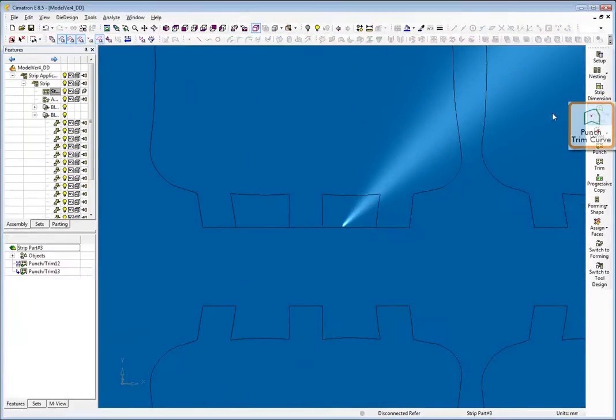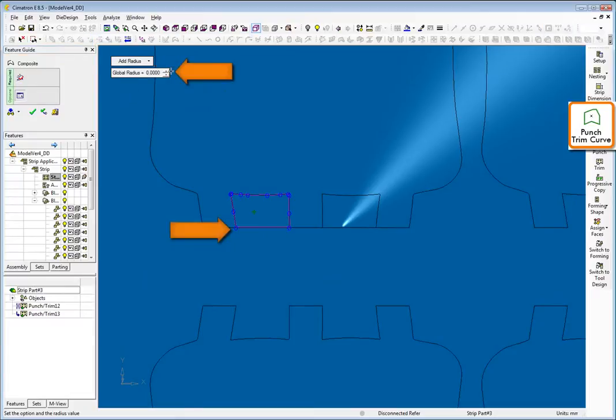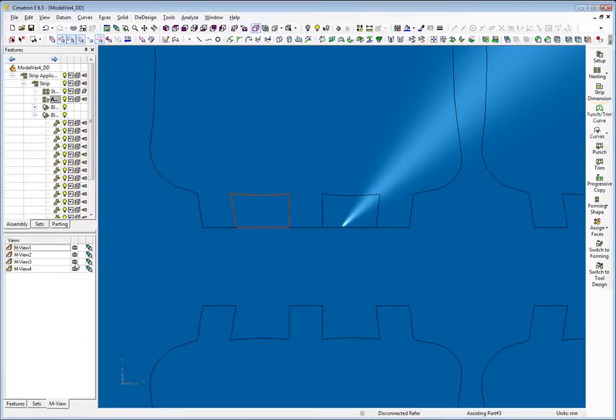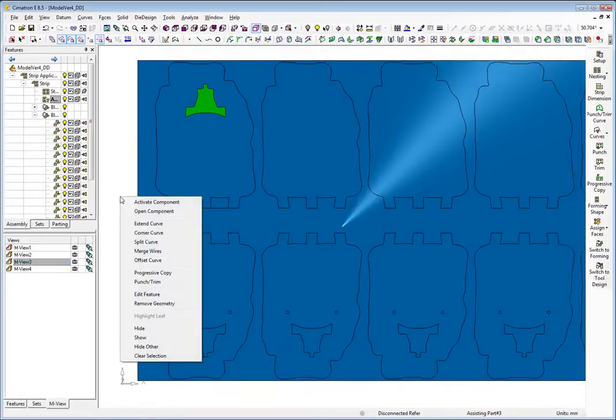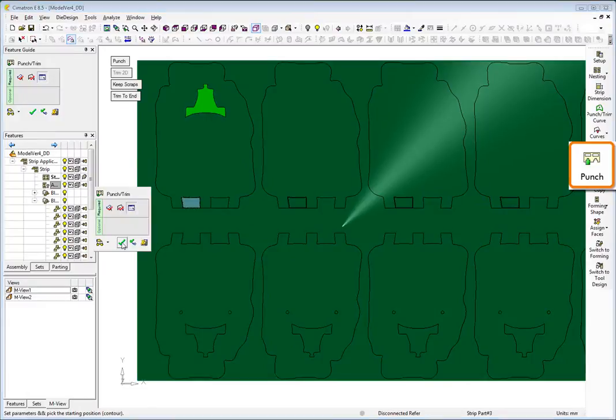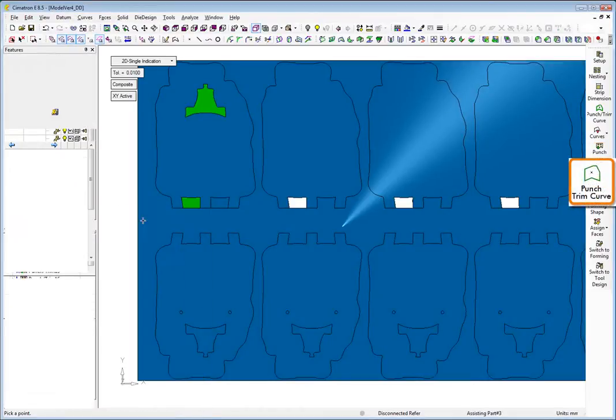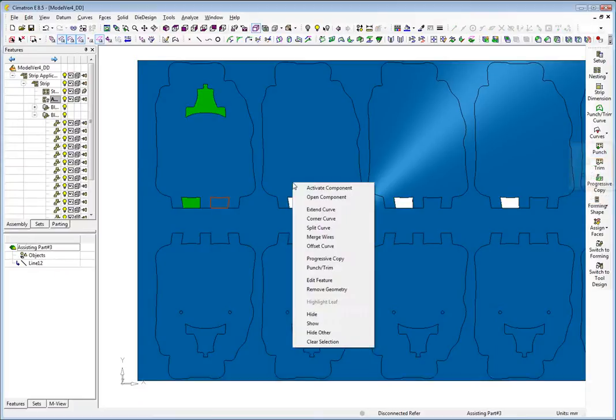We can define a contour of a punch at a single click. The system knows that you are making a punch and will automatically create it for you, including the rounded corners. Although the process is automated, you have full control on all parameters at all times. You will immediately see the impact of your operation on the remaining strip. Working too fast? Don't worry, you will have a chance to see this again several times.